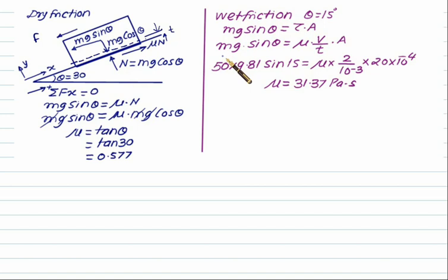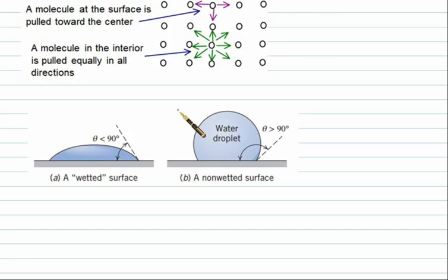Second idea is about the surface energy or the surface tension force, which is denoted as sigma and is basically force per running meter length, that is F by L. So the unit is Newton per meter. Now this quantity, Newton per meter, we can very well write as Newton meter divided by meter square. Newton meter is nothing but energy, and this one is called density. So sigma is also called the surface tension force coefficient, or energy density.